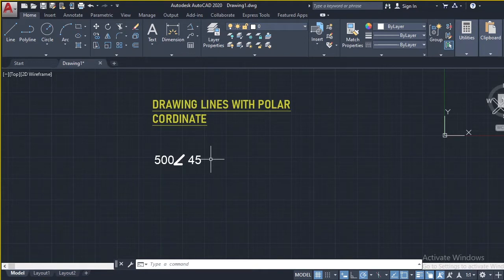So we have different ways of drawing lines in AutoCAD. You can just draw with absolute coordinate system, which is same name as the Cartesian plane. The coordinates, you can actually use that to draw in AutoCAD. You can also use the relative coordinate system to draw, and the third one, you can use the polar coordinate. So I will be talking of the polar coordinate because that is more easy and faster to use compared to other ones. So mostly that is what we'll be using throughout the video, the polar coordinates.